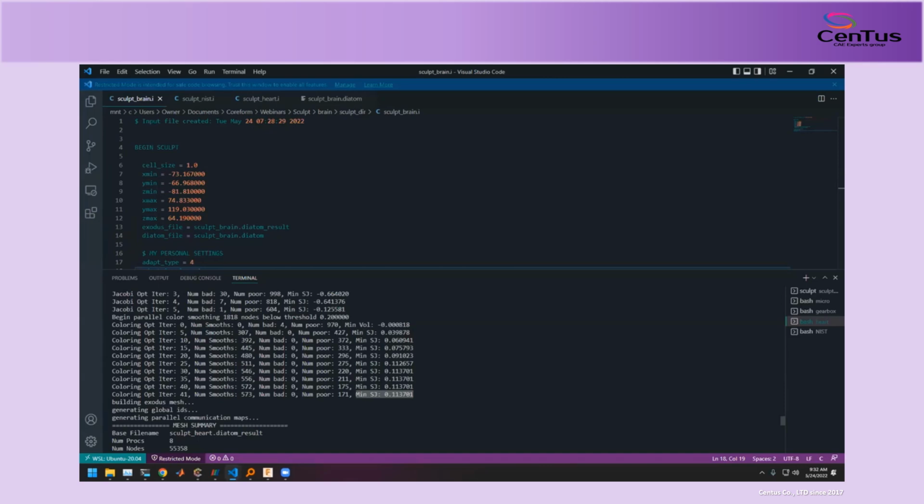What I would recommend is that when you have regions where, I can imagine, an artery, and the difference in diameter from an artery down to a capillary is quite large, that may be somewhere where you want to use adaptivity and be quite aggressive with the adaptivity as well.